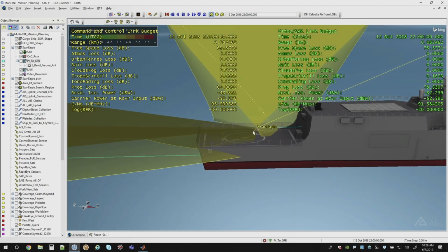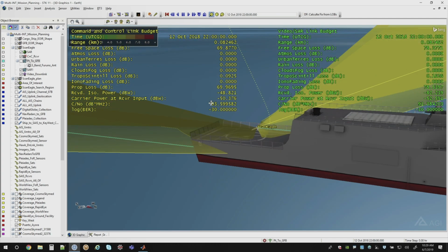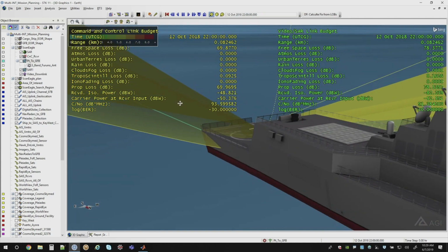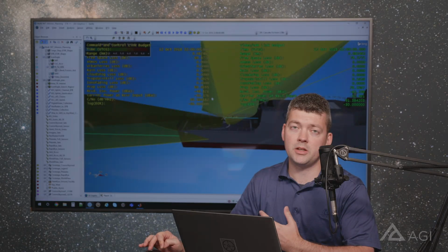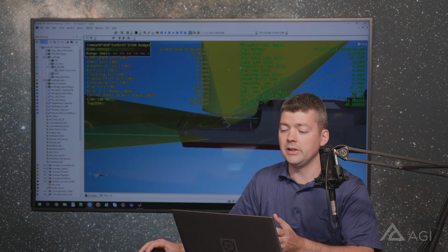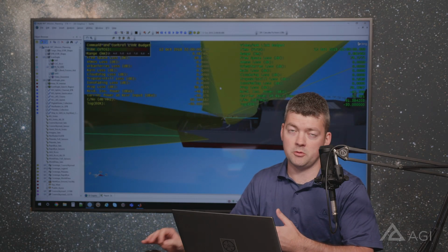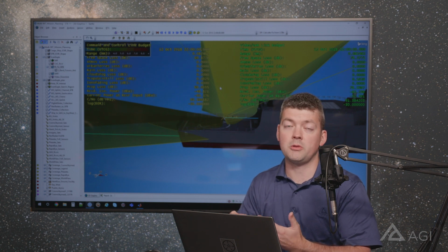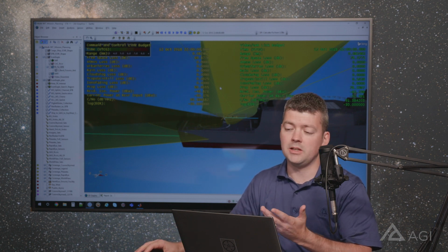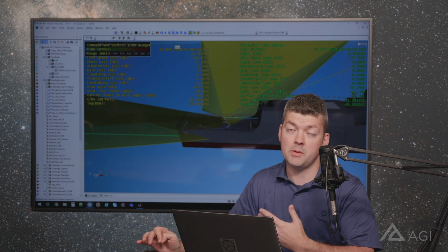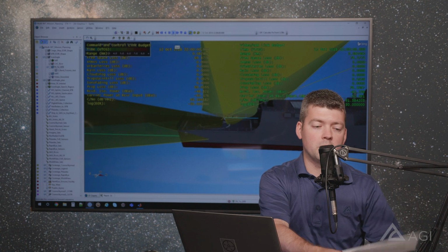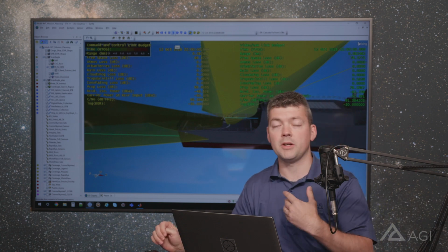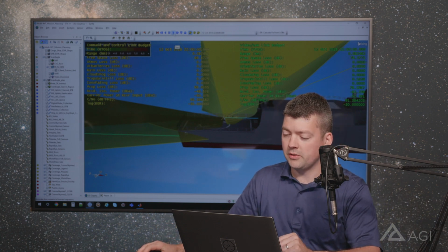So we're modeling in a generic sense, in this case, the SAR collection footprint, which is these yellow patterns coming off the side. They'll look a little more like you'd expect once it gets up to altitude. And then also we're modeling the command and control and video SAR links back to the ship for its entire route. So we're basically saying, what's a realistic route that I could actually accomplish with this ScanEagle, and could it go search my area and maybe find the cargo ship or the fast boat or something, well before my Coast Guard ships actually get up there. So we'll take a look at that.